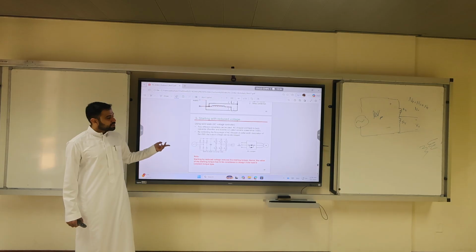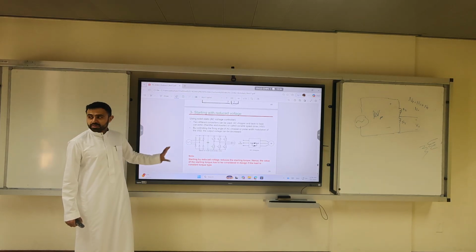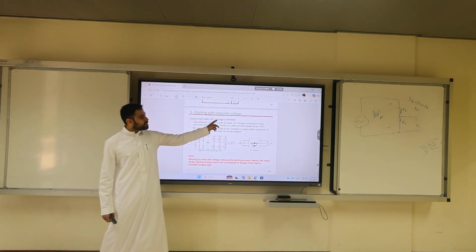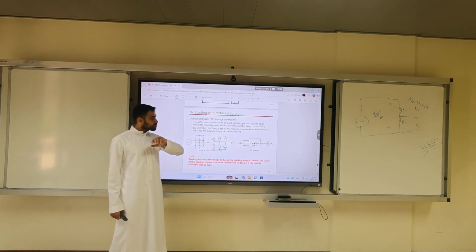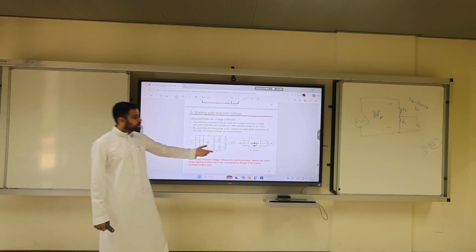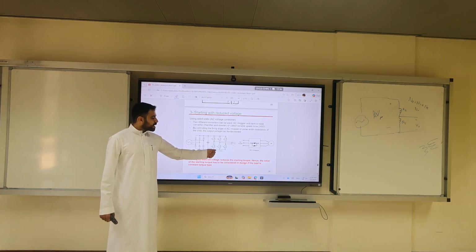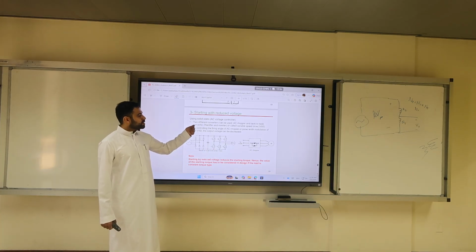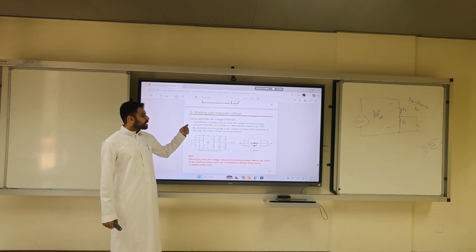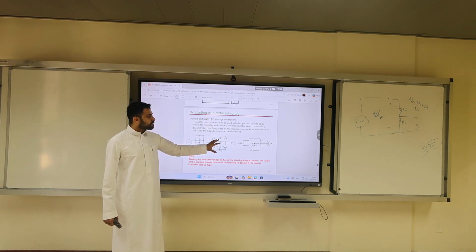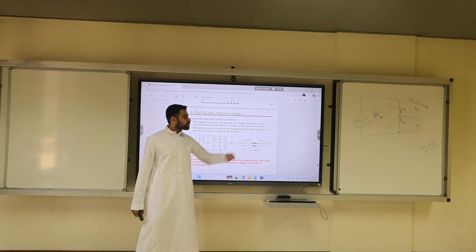And what is our favorite method? Power electronics. We use an AC voltage controller. That's the smart way, or an AC chopper. This is a back-to-back converter, a variable speed drive. Two different converters can be used. AC chopper, or back-to-back, a rectifier and inverter. This is called VSD.